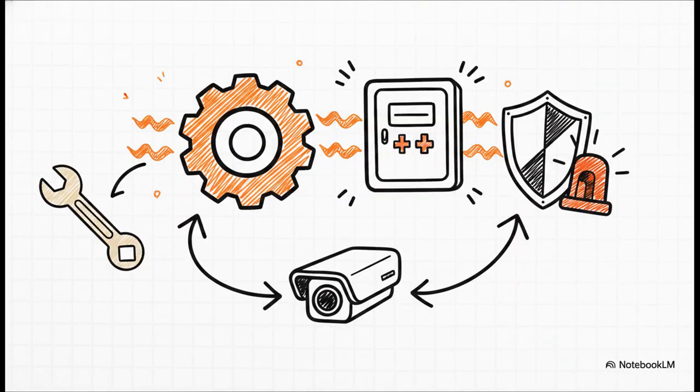Now, what's really fascinating about thermal monitoring is its dual purpose. Because it's measuring heat before ignition ever occurs, it doubles as a condition-based asset monitor. It's watching for friction in a bearing, an overloaded motor, a stressed electrical panel. It actually learns the normal temperature baselines of your specific equipment over time. So it's really doing two jobs at once. It's warning the safety team of a potential fire risk, and it's giving the maintenance team a massive heads up on failing equipment before it causes some ridiculously expensive downtime.